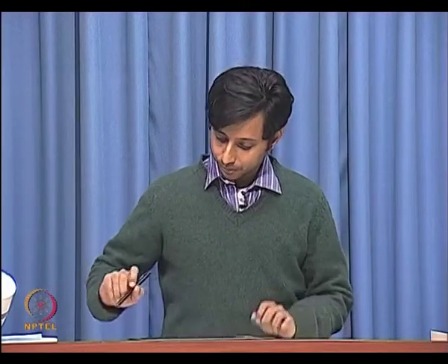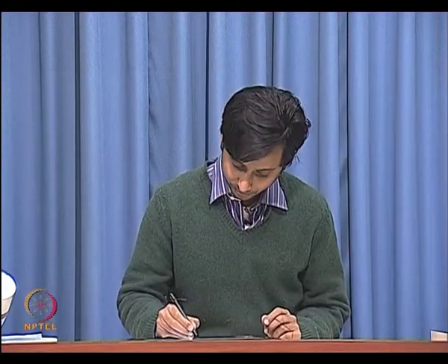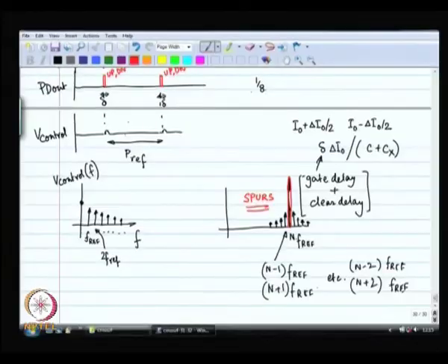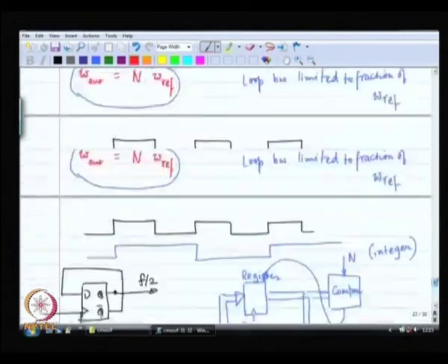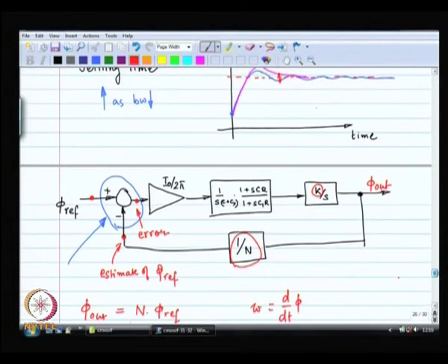All right. So, we are going to summarize all of this phenomenon. These are called spurs. Okay. So, in one word these are called spurs or spurious frequencies. So, whenever you have designed a frequency synthesizer like this, you are going to get all of these spurious frequencies. This frequency synthesizer has a name, it is called the integer n frequency synthesizer.